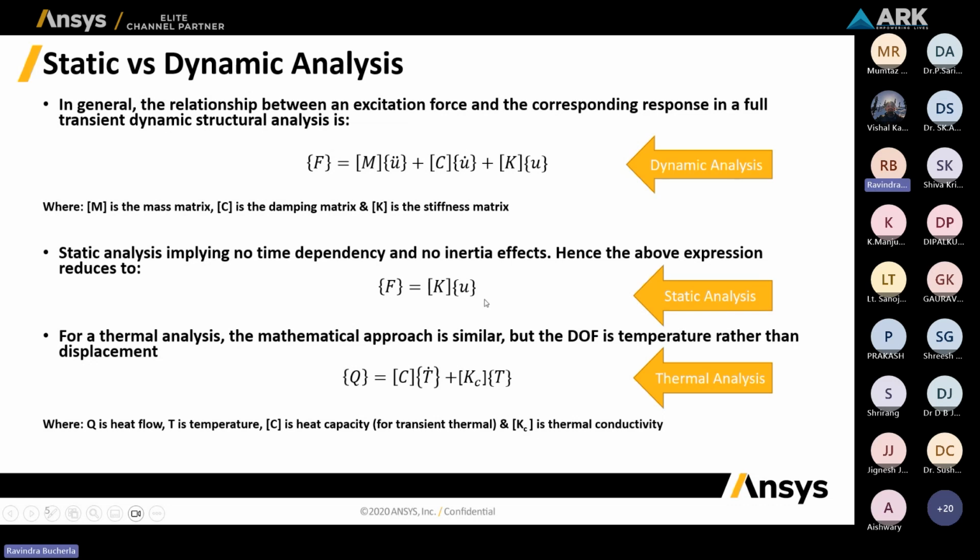So this is the equation that we will use to solve all the problems related to static analysis. But whenever there is a time dependency, obviously the inertia effects will also be included in that problem. So that problem we generally consider as a dynamic analysis, where we will have a mass matrix, acceleration, damping matrix, and velocity as well. If the problem depends on time, like if any one of the components is moving with some velocity, or if you are applying the load with respect to time, this kind of time dependency problem we will consider as a dynamic analysis, where it will have the inertia effects as well.